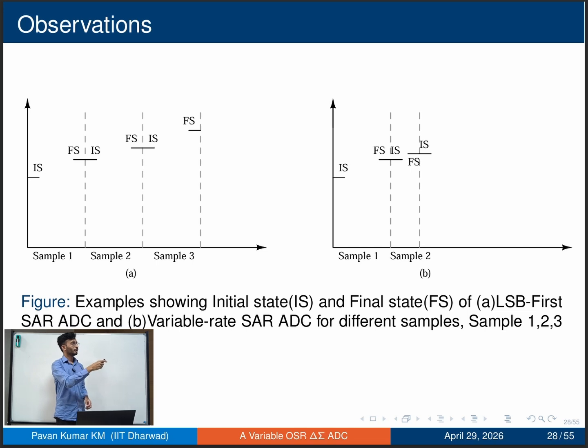In this implementation, since we are starting a new cycle after each conversion, the period of conversion for each sample will be different, and it is reduced. We can observe that. Since the sampling frequency has increased, the consecutive sample difference will be reduced much further. Thereby the upcoming samples we can converge much faster.